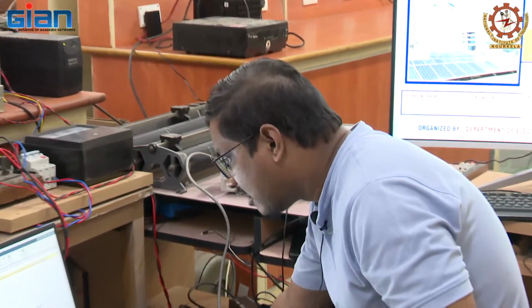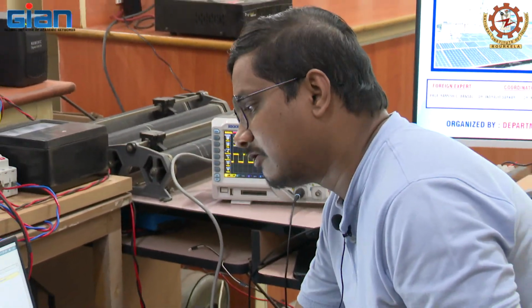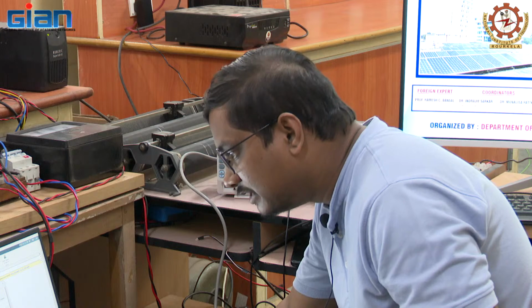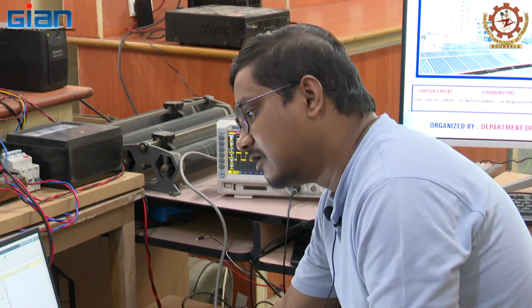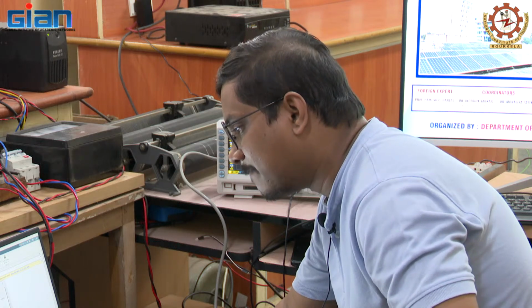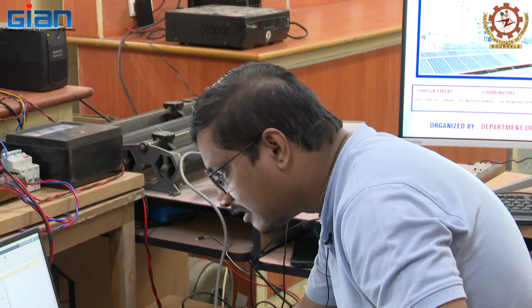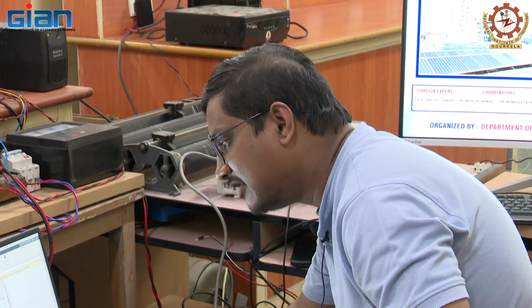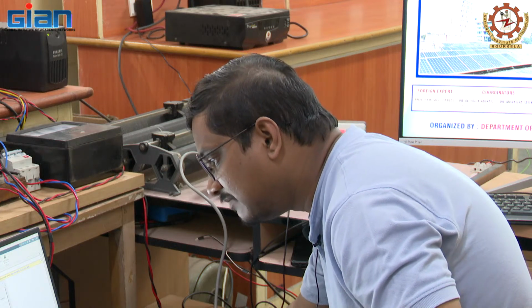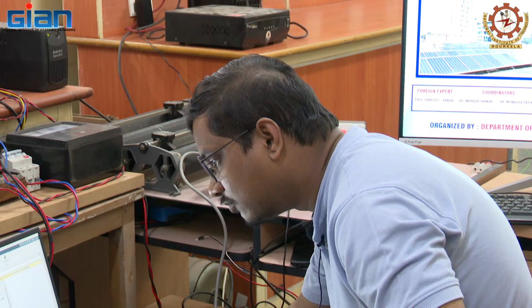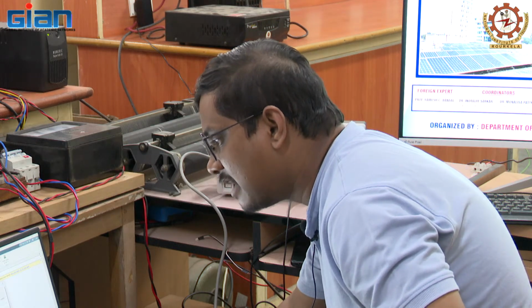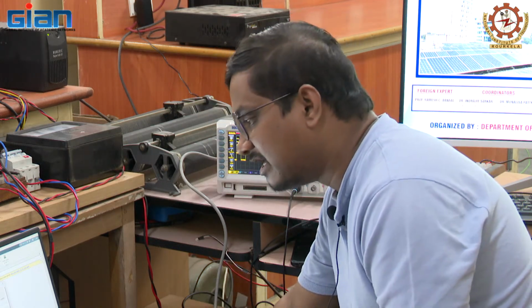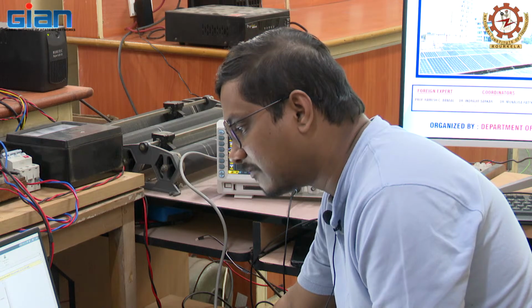Similarly, here you can see that I am now using EPWM1. If you want to use 1B also, we can use EPWM-B, enable it and set the actions. Then similarly compare A is given from input A. In a similar way you can give compare B also from input port B, and if you want the deadband also, we can use EPWM deadband for both of them.